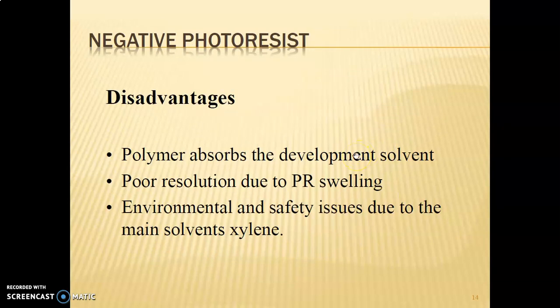A disadvantage of negative photoresist is that the polymer absorbs the development solvent, giving poor resolution due to photoresist swelling. There are also environmental and safety issues due to the main solvent.